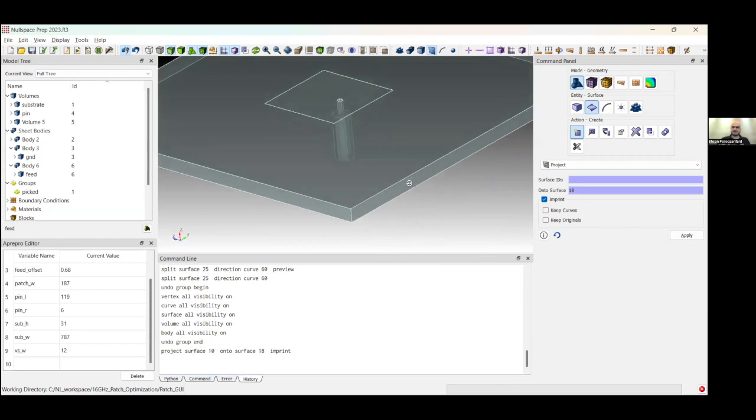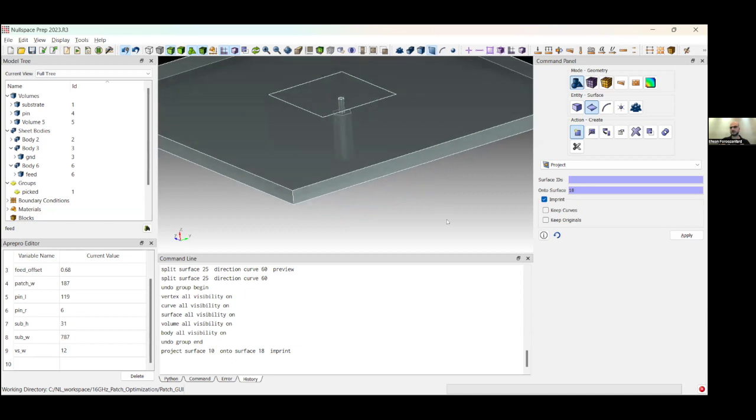Now we have done all the CAD creation part. So we want to go ahead and do the Boolean operation on different parts. The reason we need to do this Boolean operation is because if there is an overlapping of volumes, then we need to subtract the overlapping parts. And that's really important for the mesher to know, because if there is overlapping, the mesher will try to mesh those parts two times and then create an invalid mesh. So that's why the Boolean operations are really important to do before we step into the meshing part.